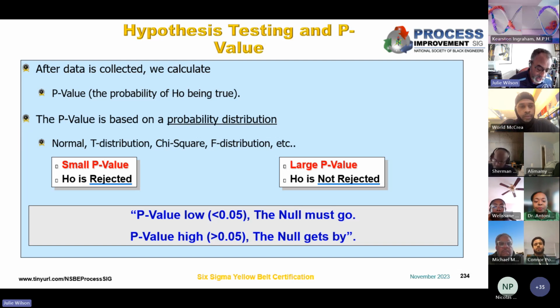And so the way you assess the risk is, do you put the risk on shipping out a product that's defective and putting the risk on the hands of your customer? Or do you risk throwing away good parts in your factory and losing money? So that's kind of the practical implication. And it's all driven by how you set up your hypothesis tests and the resulting scores. I'll say one more thing about the p-value, and I'll go back to when we talked about graphs.